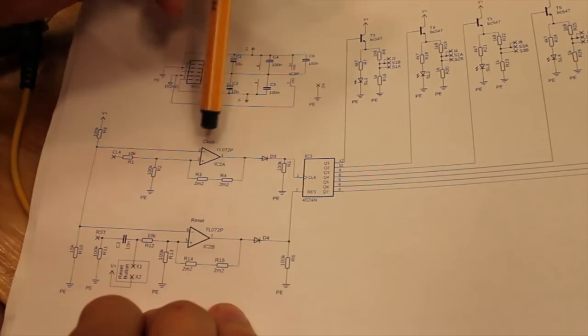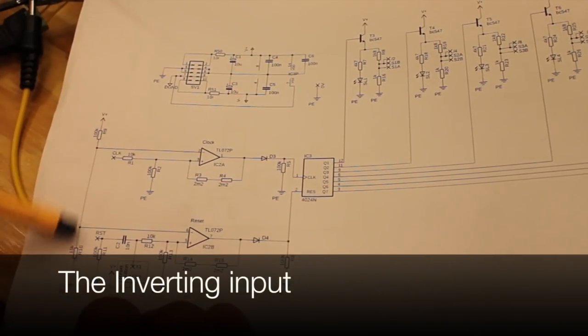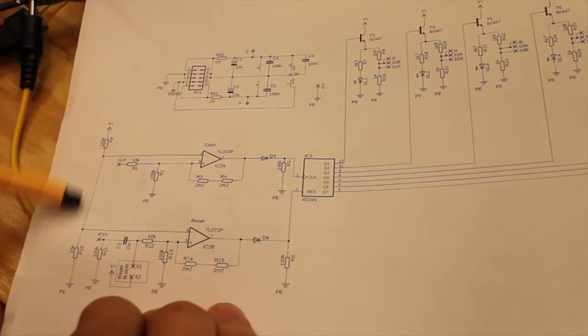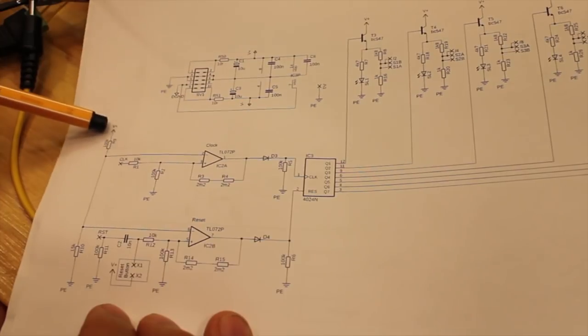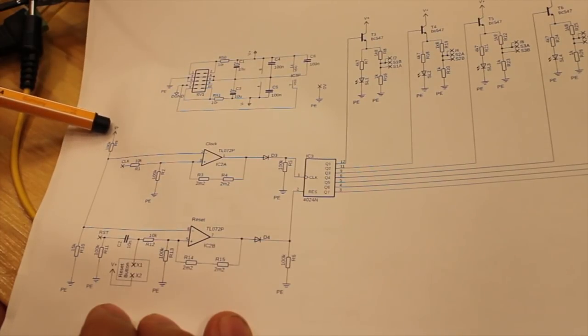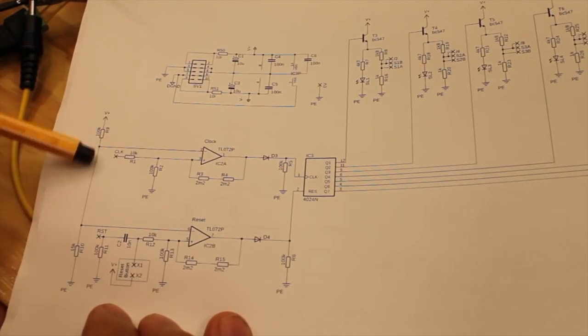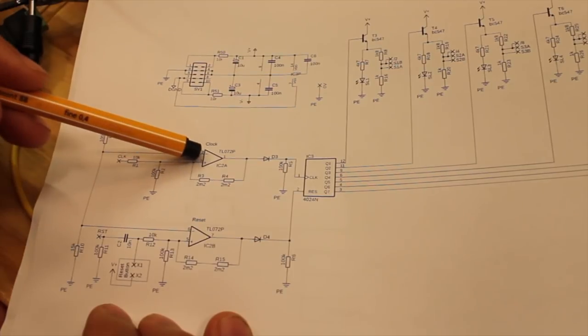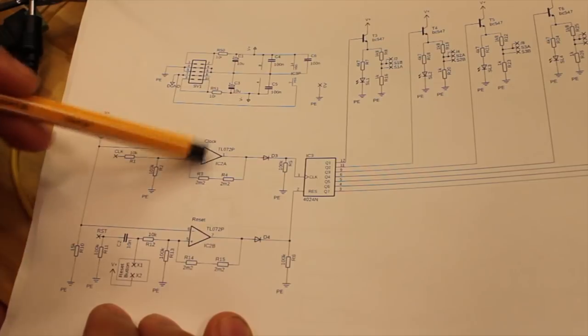Now, the interesting thing is that the negative input is connected here to a voltage divider. So this is connected with a 100k to voltage plus, 12 volts in this case, and a 15k to ground. And this means that the negative input is at around between 1 and 2 volts.